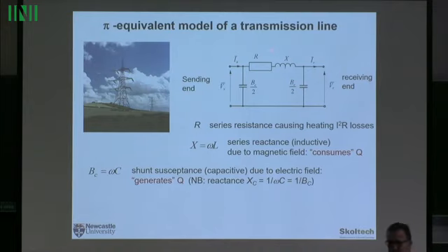And I mentioned, I can't remember whether it was in the lecture or break, that the transmission system operator will switch off some of the lines at night. Now why? Because during the day there's high current flowing, which means the inductive effect is much stronger than the capacitive effect. So a line is a net sink of reactive power and voltages go down.